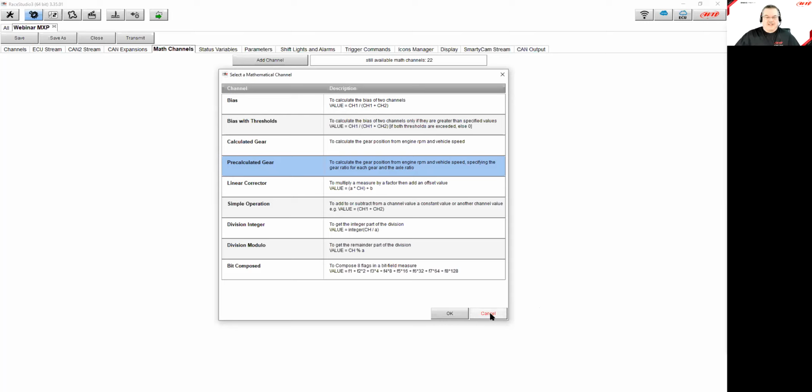One of the ones that I have in here a lot, and I showed it in a couple of webinars ago, is front brake pressure and rear brake pressure. Certainly, in the software later we can create that bias channel and then look at what the driver actually had, maybe hand adjusted in the car to get the car to handle correctly. But we can actually do that on the display, as Robinson just mentioned, and then when the team is getting ready for the driver to go out, they can jump in the car, push on the brake, and see the front and the rear brake pressure, and have the actual front brake bias percentage shown to them right there.